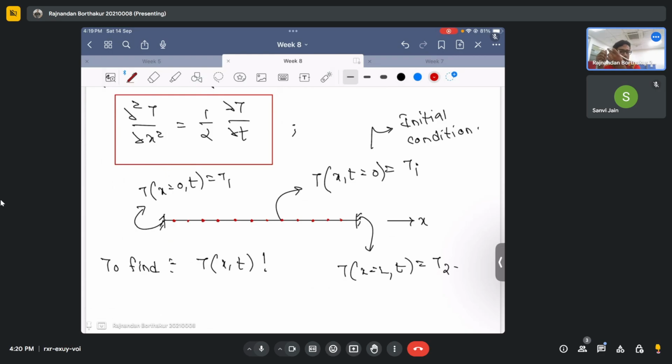Also, there is something known as grid independence, which means that after choosing the number of grids up to a certain level, let's say I take 1000 grids here, if I increase the number of grids further, the solution would not vary much. This is known as grid independence. So people say grid independence is reached after, say, 1000 grids.